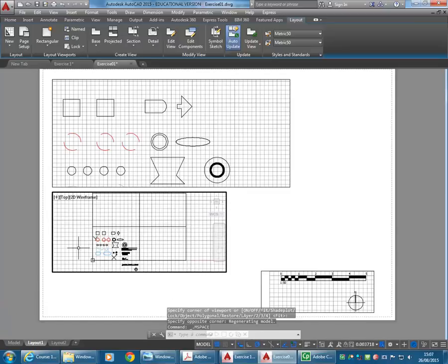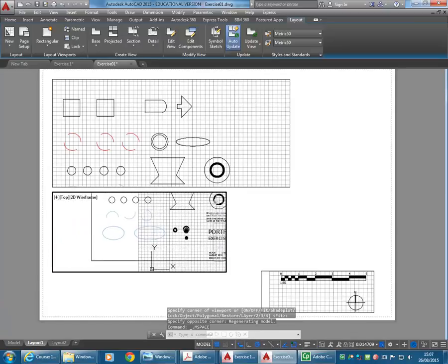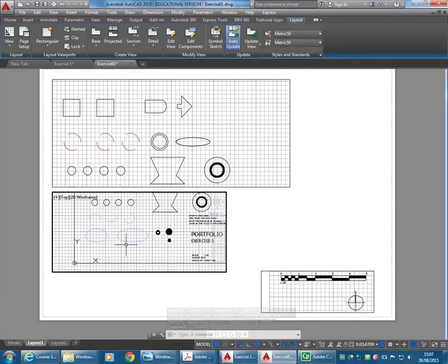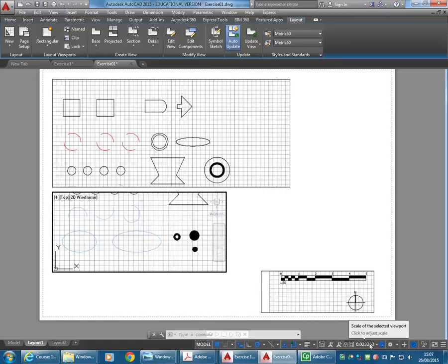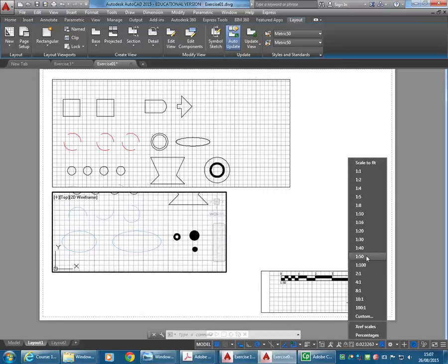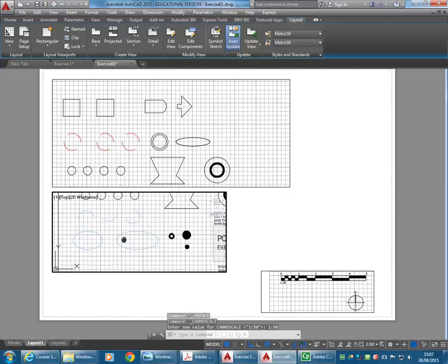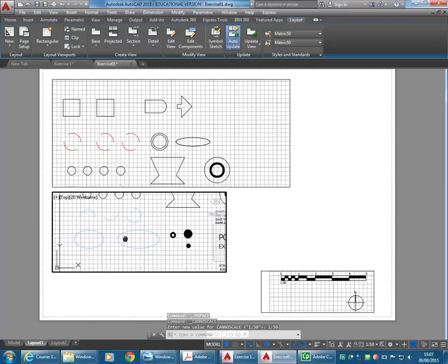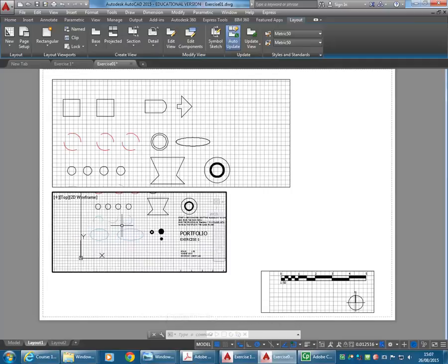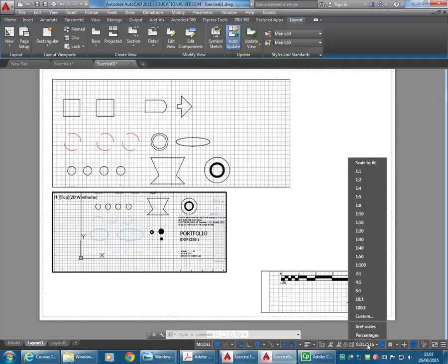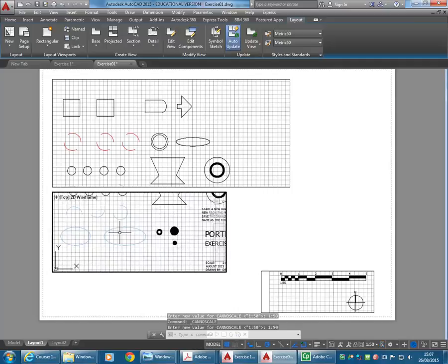Again, click on the paper button, zoom roughly to the location you want. So I want to get these parts here shown separately. Then set your scale accurately. So for all of these it will just be 1 to 50. So you can pan as much as you like after that. That won't affect the scale. But remember, if you zoom, zooming is the same as scaling. So zooming changes the scale, and you can see that the numbers there have gone crazy to something that's not very useful. So you can just change that to 1 to 50 again and try not to zoom.